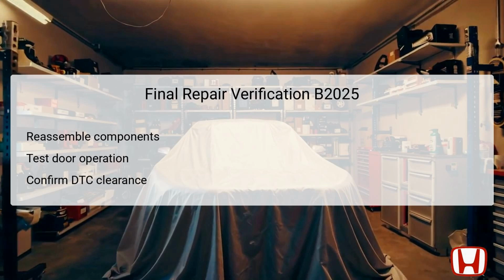Once all necessary repairs or replacements are completed, the final task involves reassembling the components and ensuring all connections are secure. After putting everything back together, physically testing the power sliding door's operation is paramount. This ensures that the door responds properly to the switch inputs. Finally, run a diagnostic check with the HDS to confirm that DTC B2025 is cleared from the system. Proper verification guarantees that the repair was effective and that the power sliding door is functioning as intended.